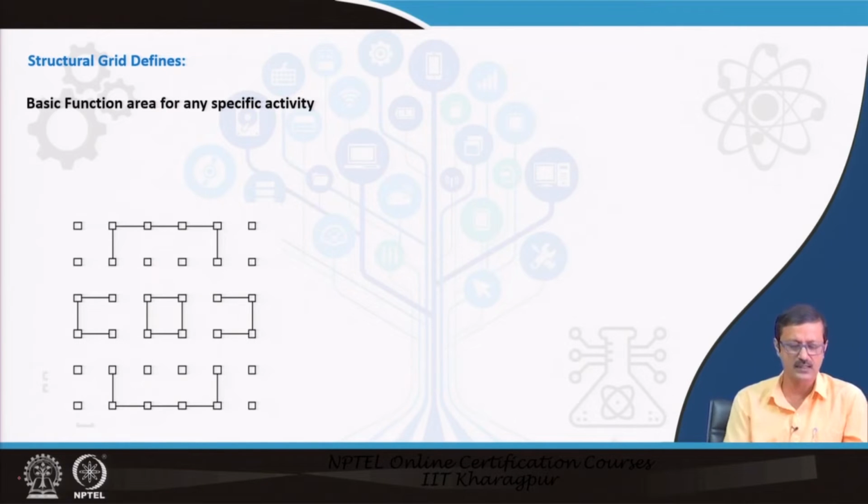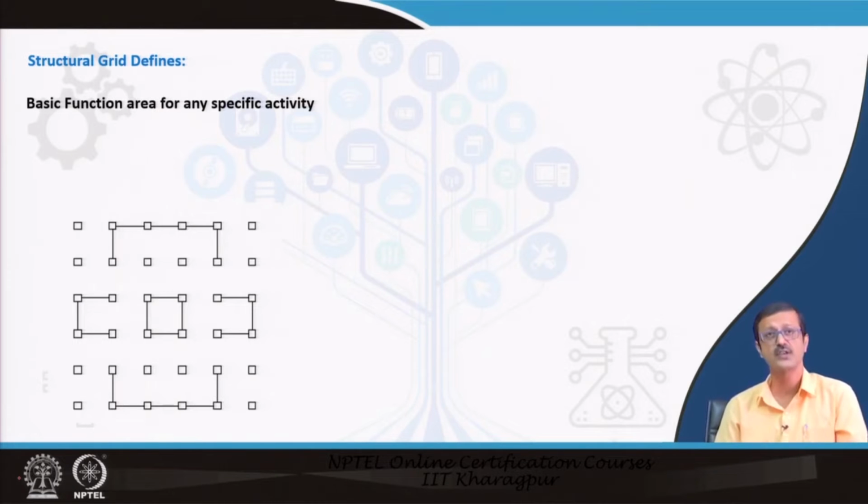So, I have a circulation zone and a display zone or something like that. Maybe there is an entry at one end, at another end a cafeteria, and there is another part, a souvenir shop. So, I have activity zones all around, and because of the requirement of the activity zone I give 3 grids or 3 bays to a particular activity, one central bay for some activities or something like that.